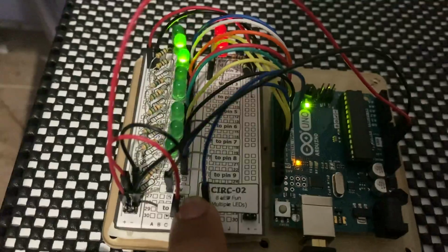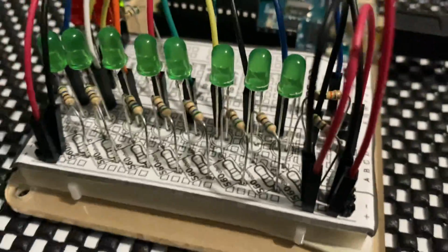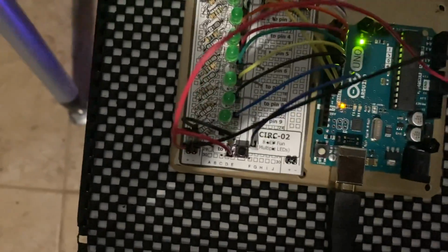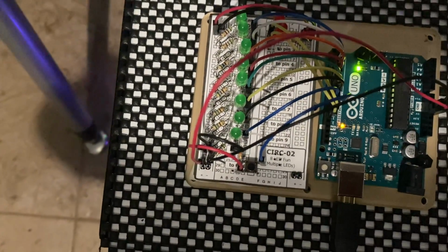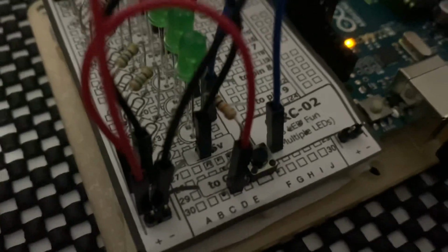And to be completely honest, this was a lot of work to get it working. The green LEDs stayed the same. They're connected to the ground via their 560 ohm resistors. For the button, I had to go ahead and rewire 2 extra wires, for the ground and for the 5-volt power line, over to 2 different pins on the button. One is directly on the button, and the ground pin is connected via a 10K ohm resistor right through there.